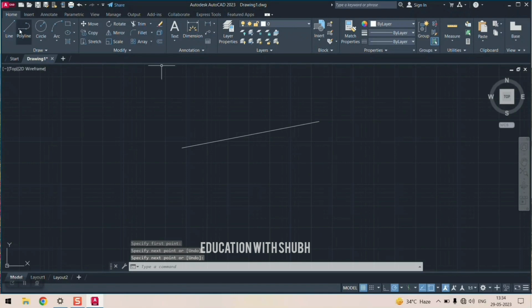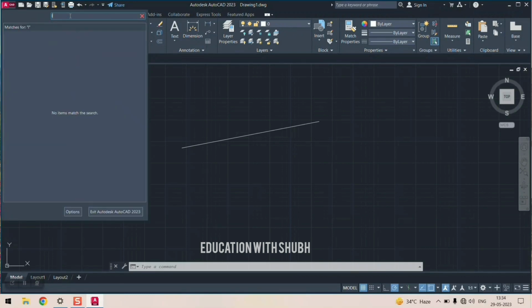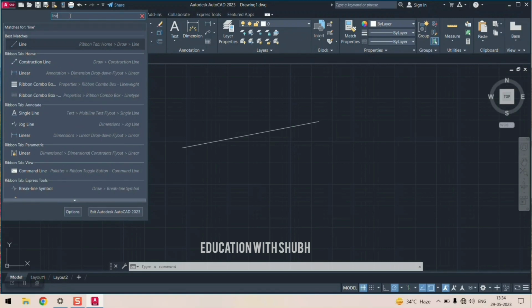Correct. There is another option: if you forget something, like if you don't know where the line command is available, where I will look for it, then you do one thing. You just go to the application menu. This is your application menu. You just go to this and click on the line command. It will give you the line. This is the third option available. In this option there is an advantage of both the command line as well as the manual location of the particular command. So this particular searching will help you in creating a line command.